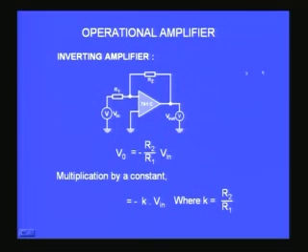Now I have here a very simple circuit which you might recognize as part of the old circuit that we already discussed. Here what is happening? You find there is a feedback resistor R2 and R1. This is actually minus and this is plus, it is not seen here. So the feedback is negative because the output is connected to the negative input, and therefore it is a negative feedback using two resistors R1 and R2.